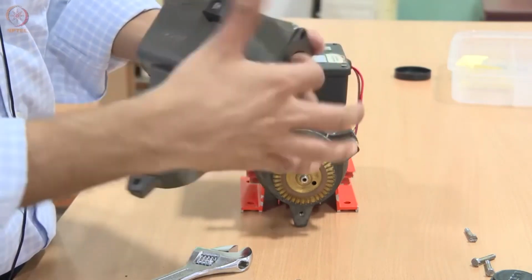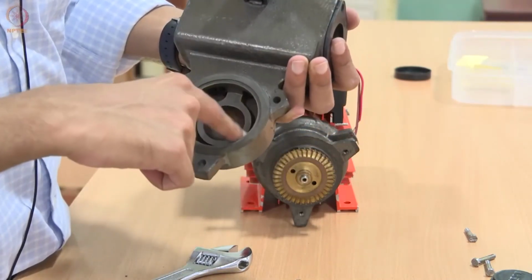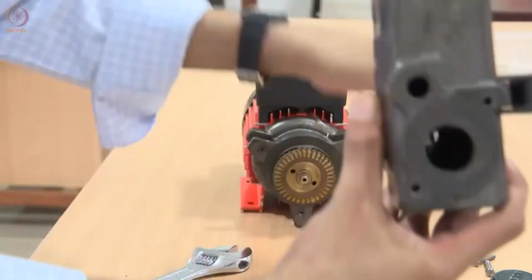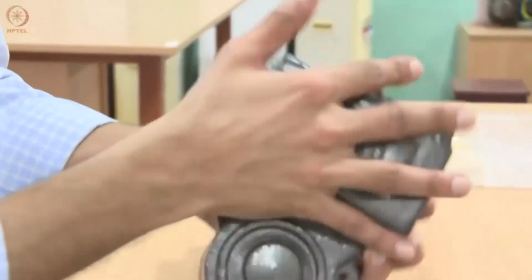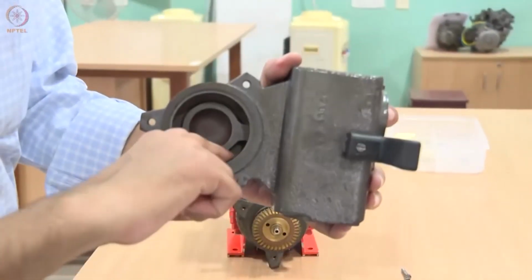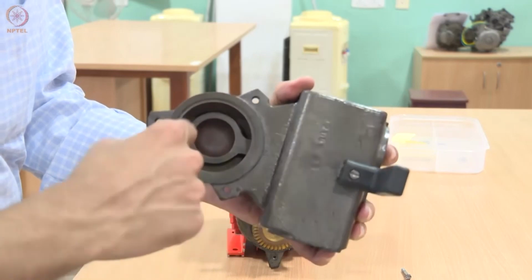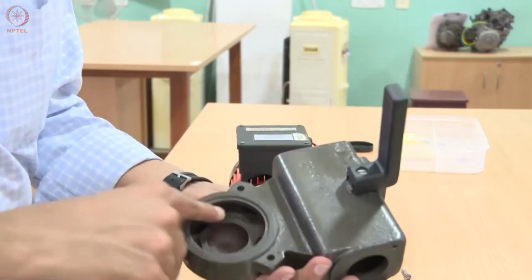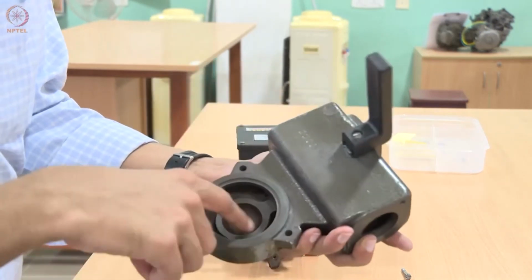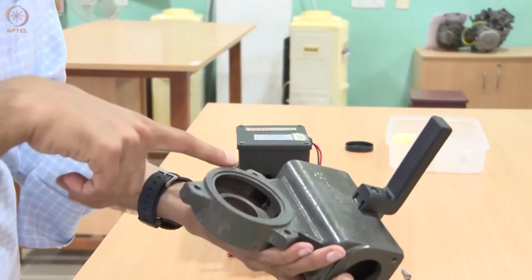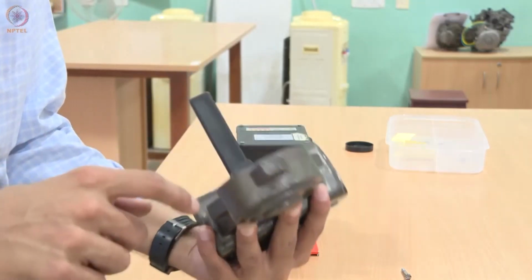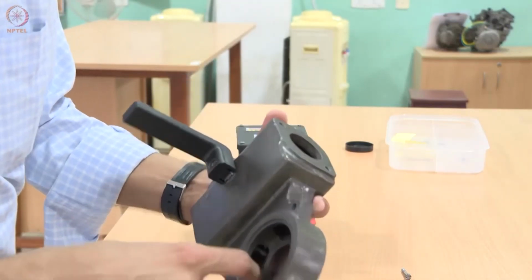Remember, this entire top portion and the casing is filled with water, and then it goes around and exits out through the top. You can see there is a wall separating here. So water enters this way, you can see my finger here, comes around the annular region, and then again enters a little bit tangentially, and exits a little bit tangentially. Not strictly tangential, but almost tangential.